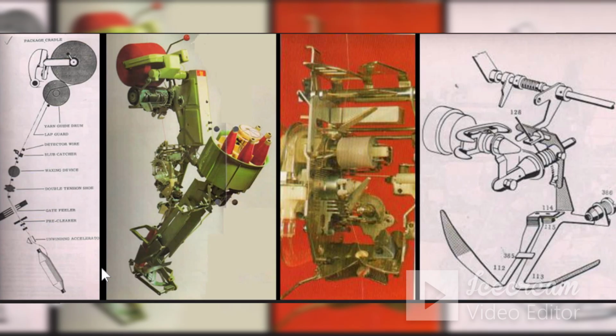Now, the question may come that why do we not sense on the ring frame bobbin to know whether it is exhausted or not? The reason is that during the splicing or knotting cycle, the arm that picks up the yarn from the supply package takes up the yarn at this point, that is at this location.